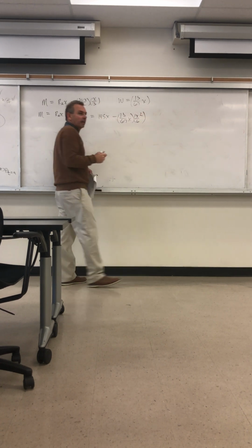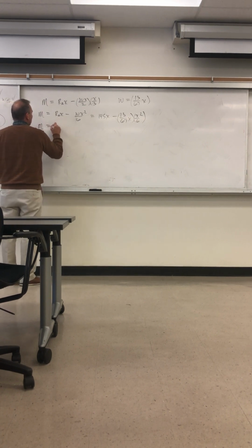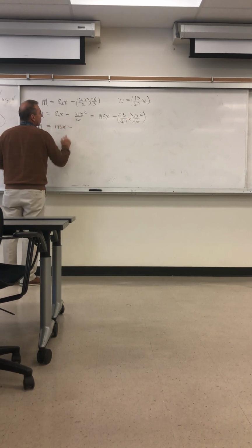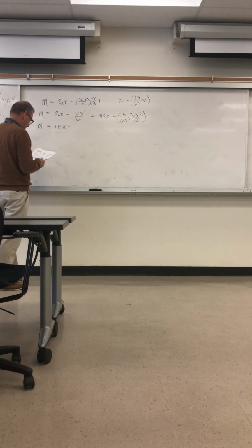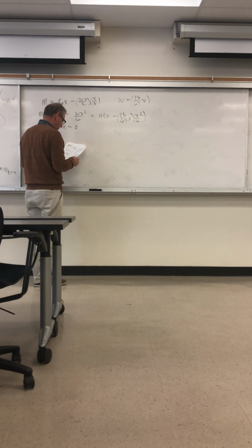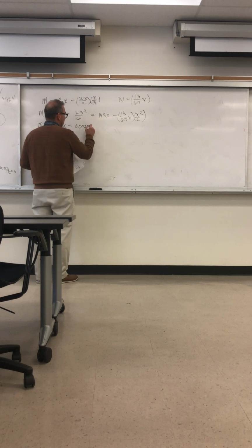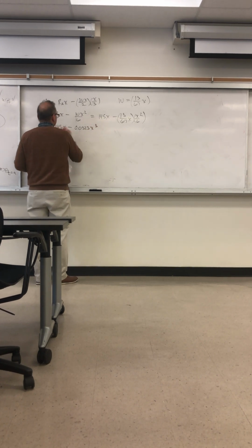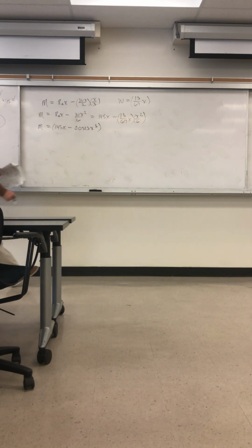So in this case, we're going to have an x cubed term. You see that? So we have the moment is 145 times x minus, switching from fractions in my notes to decimals, 0.0323 x cubed. That's just 13 over 6 times 67. Rounded off, 0.0323, 3 significant figures.